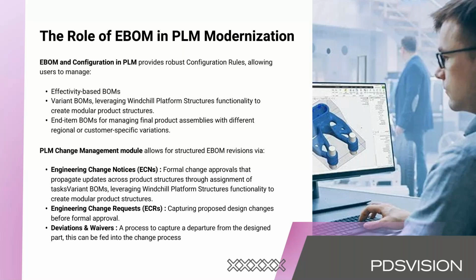So EBOM and configuration management in Windchill. Configuration management is a core strength of Windchill PLM. The system provides robust configuration rules, allows users to manage effectivity-based BOMs by things like serial number or date-based configurations, variant BOMs leveraging Windchill platform structures functionality to create modular product structures, end item BOMs, which is something we spoke about, for managing final product assemblies with different regional or customer specific variations.